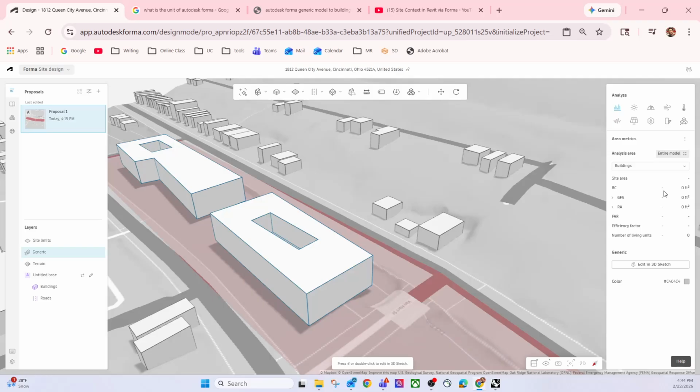If you recall Revit, you have a massing model which is generic, but you can definitely create other details out of this massing model. So the way to do it is I can make a selection of this. Let me see if we are able to add floors directly into this massing model.